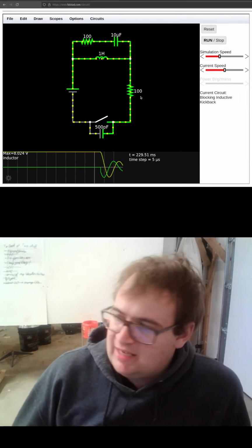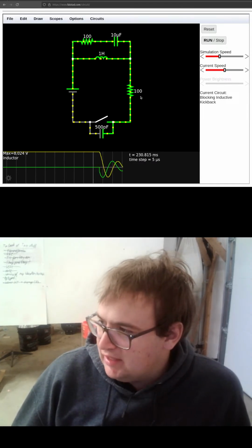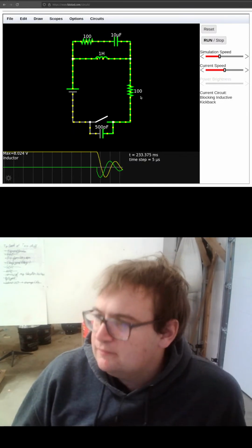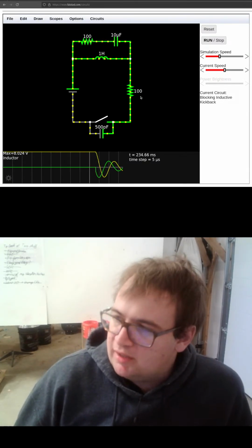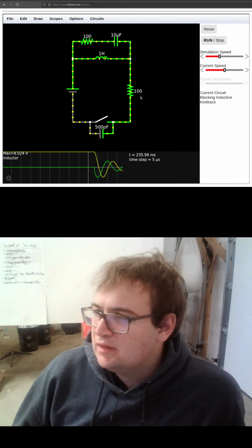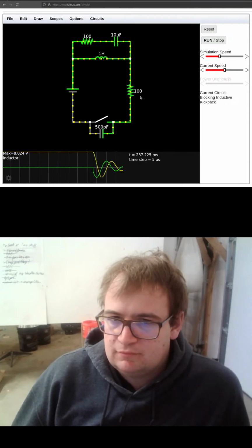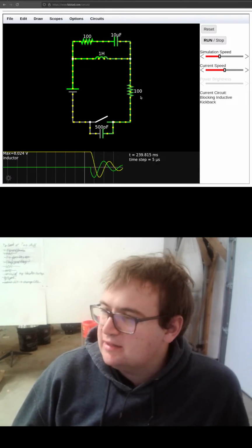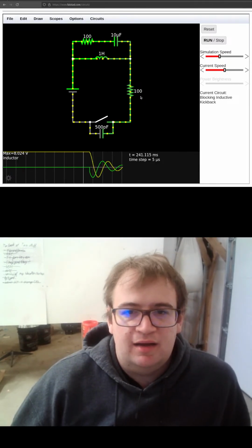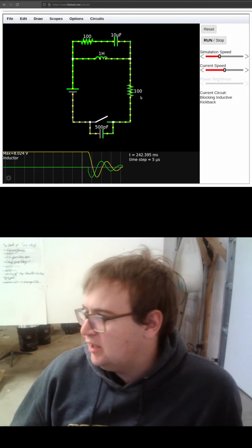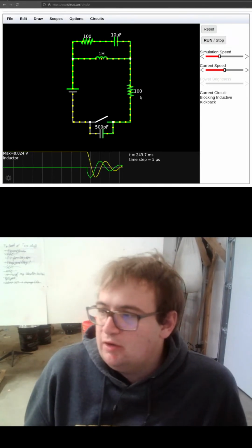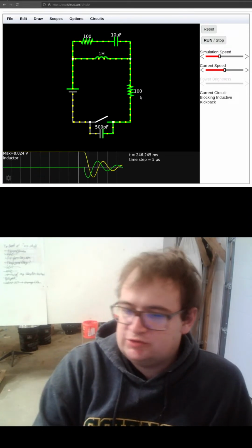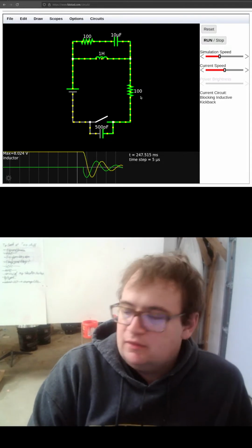Going back to the textbook I was reading, Learning the Art of Electronics, the way that they dealt with it was they just put a diode that would go into conductive mode when that inductor started to blow itself up, which both are fairly valid.